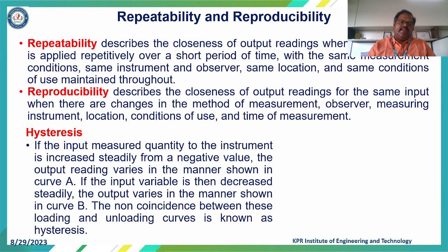And repeatability and reproducibility. Repeatability describes the closeness of output readings when the same input is applied repetitively over a short period of time with the same measurement conditions. Reproducibility describes the closeness of output readings for the same input when there are changes in the method.